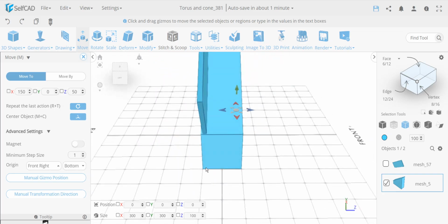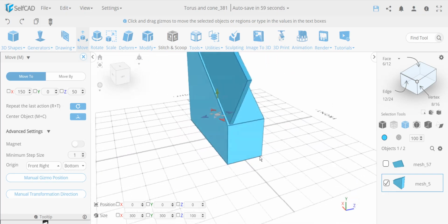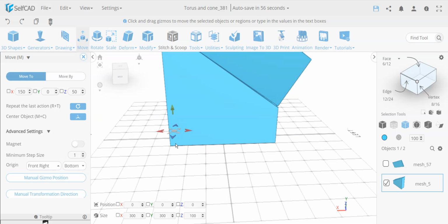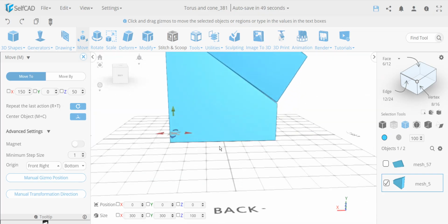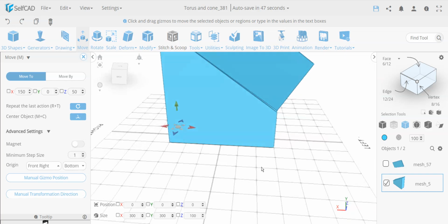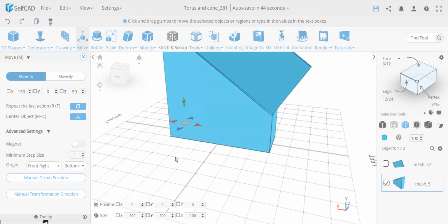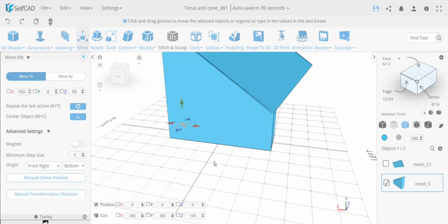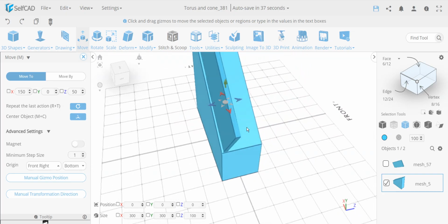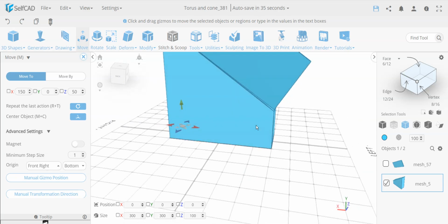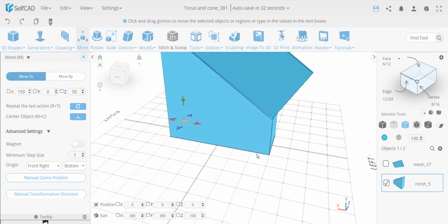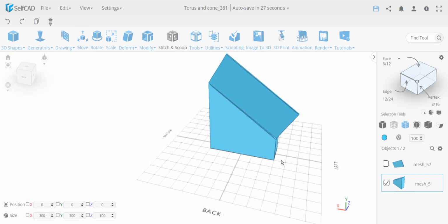Now, just to summarize quickly, what we have over here is a scene that must have a system. We don't actually have a way to change the pivot point from the scene. The pivot point from the scene will always be the bottom center from X and Y, and from the height will be the bottom, but other sides will be the center. And what we can change is we can decide to use a face to give us a custom direction or manually give it a direction, and we can also change the pivot point from the object to measure from different sides.